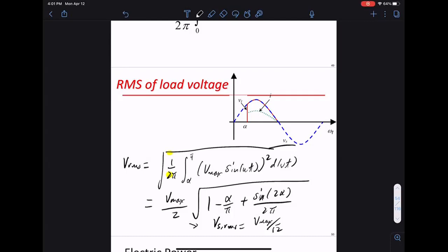The actual voltage that we see every day is basically VRMS. Almost all for AC, for anything that has a sine, even after rectification, the V you see is the RMS voltage. Because what you really want to say is that V squared over R is power. Whatever V gives you that equation, that's the one we want, and it turns out RMS voltage works for that power equation.